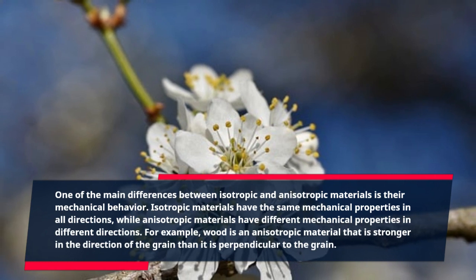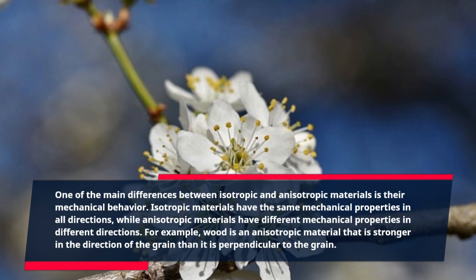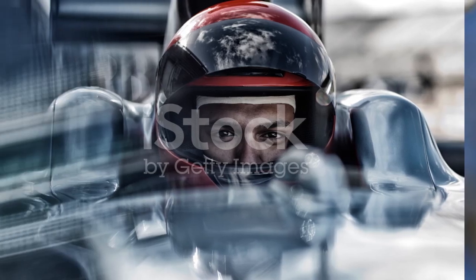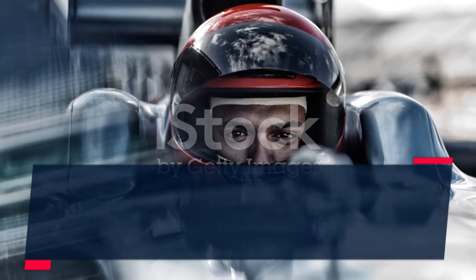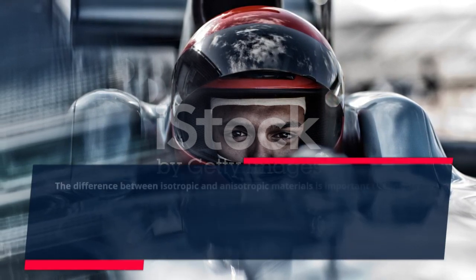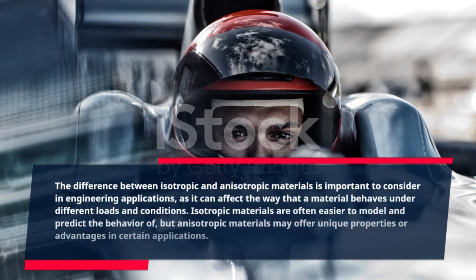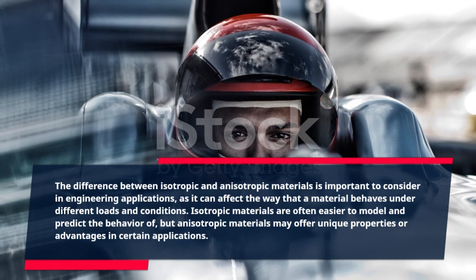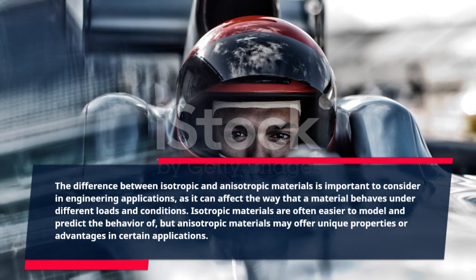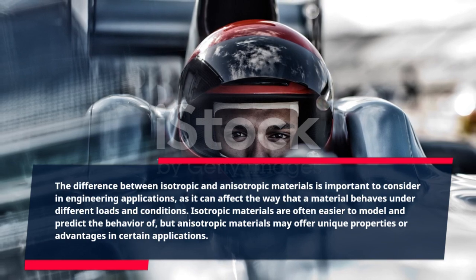For example, wood is an anisotropic material that is stronger in the direction of the grain than it is perpendicular to the grain. The difference between isotropic and anisotropic materials is important to consider in engineering applications, as it can affect the way that a material behaves under different loads and conditions. Isotropic materials are often easier to model and predict the behavior of, but anisotropic materials may offer unique properties or